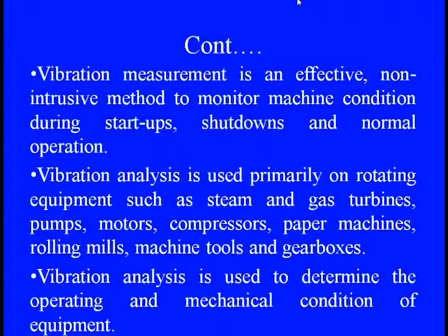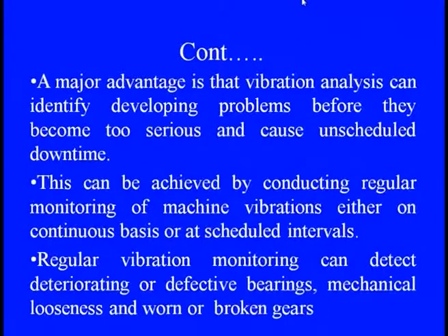So, vibration analysis is used to determine the operating and mechanical conditions of the equipment. The major advantage is that vibration analysis can identify developing problems before they become too serious and cause unscheduled downtime of the entire system. And we achieve this by conducting regular monitoring.